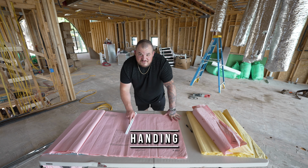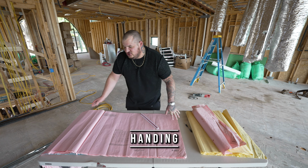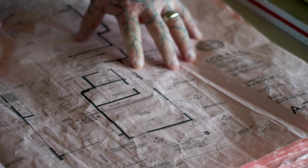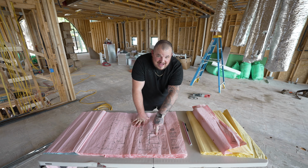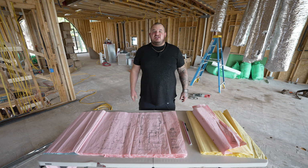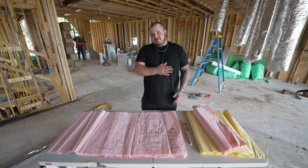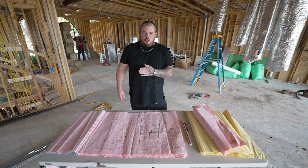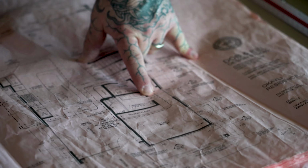Another thing that is very important when it comes to doors is called handing. Let me show you what that means on the plan. Now, when you're talking about handing, picture that your back is against where the hinges are on the door. If the door opens this way, this would be a right-hand door. If the door opens this way, it would be a left-hand door. And that's very important.